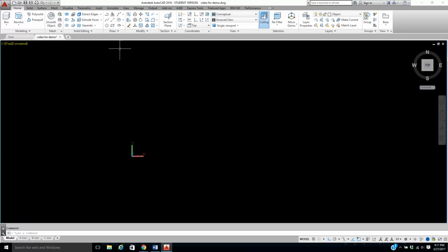All right, so let's start off with just a polyline, because remember, this needs to be all one continual piece. Now remember, if we draw this in lines or arcs and trimmed it, we can put it all together using our p-edit command or using our region command, which I have both of those as the video. So let's start here, and let's start out with a line across the base of our bowl here. Okay, now remember, I'm going to take ortho off.